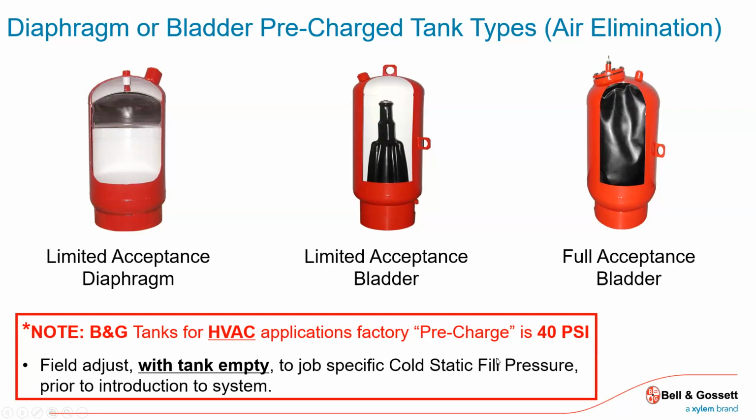So they're going to be responsible on day one when they're installing to address that. We'll talk a little bit about that, but that's important because a lot of times the guys downstairs will get the call after a job's commissioned and all of a sudden relief valves are blowing. Something's wrong with your tank. We think the bladder's busted. I'm like, well, that happens. Things happen. Why do you say that? Well, we just filled the system, attached it, we just fired the boiler plant, pressure rose, relief valves dumping water all over the place.